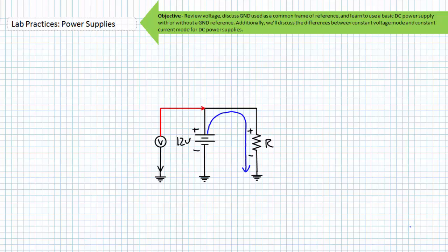Beyond simplifying schematic drawings, if I took my reference probe and placed it on a point hooked to ground, even if it wasn't directly inside my circuit, I could now measure differential from ground with only the high lead of my voltmeter. Not only does this vastly simplify schematic drawings and voltage measurements using common points of connections and frame of reference, it has important safety considerations too.